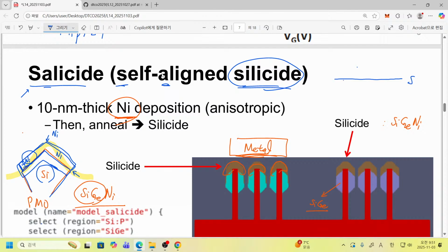Originally we have silicon and we introduce oxygen atoms by some means, for example, water vapor or O2 gas. We apply this oxygen into the silicon. Then what will happen? By reaction between oxygen atoms and silicon atoms, it becomes a layer of silicon dioxide.